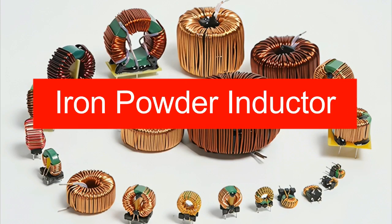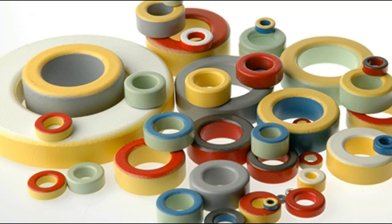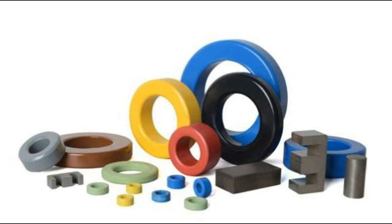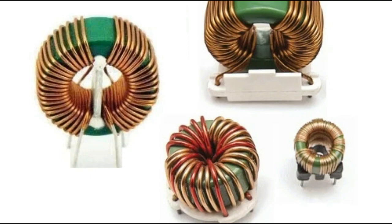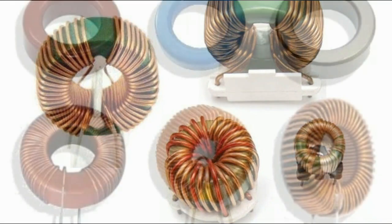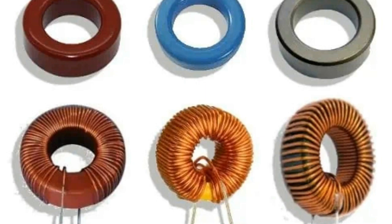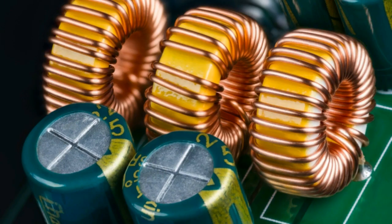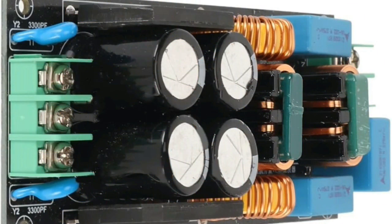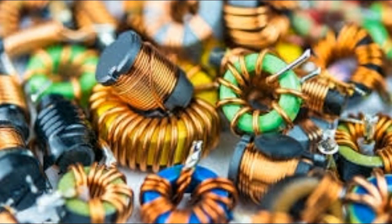Iron powder inductor. An iron powder inductor is an inductor that uses compressed iron powder in its core. This core material makes it possible to create a magnetic field around the inductor so that when an electric current runs through it, energy is stored in the form of a magnetic field. These inductors have the ability to give relatively high values of inductance for their size and are well suited for all types of electronic products where space and cost need consideration. These inductors are also used in power supplies, filters, and radio frequency circuits.